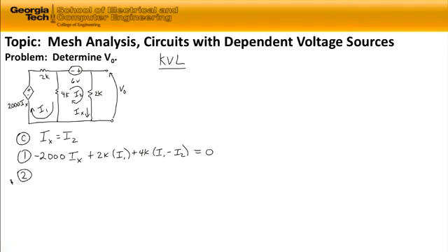And again, we have three unknowns. We have I sub x, we have I2, and we have I1. That's our three unknowns in our equations that we're going to come up with. So if we come up with a third equation, then we can solve for I1, I2, and Ix using various techniques for solving equations simultaneously. So let's add up our voltage drops around loop 2, starting in the lower left-hand corner, first encountering the 4K resistor. We know the voltage drop there is 4K times (I2 minus I1), going clockwise around loop 2.